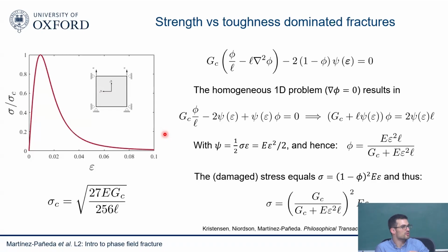We know that the damage is spread over a certain region. So that length scale, since it tells me where my damage variable spans, basically tells me how thick my interface region should be, how big my fracture process zone is. So it must be a material property because, for example, very brittle materials have a very small fracture process zone. Metals have a very large fracture process zone. Damage is occurring over a long area, whereas in brittle materials, it's a very small area where damage is occurring.